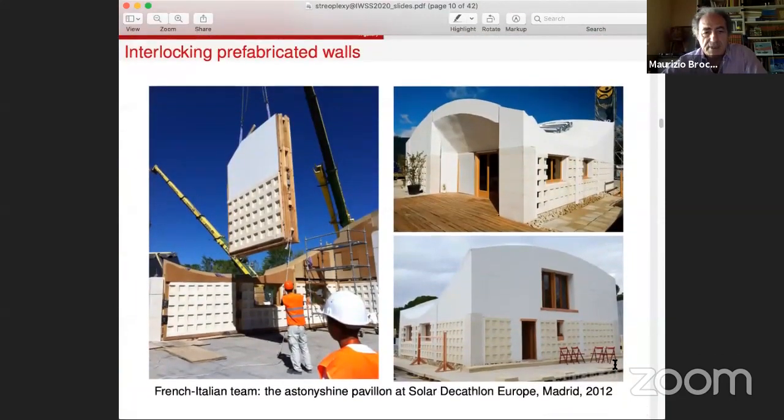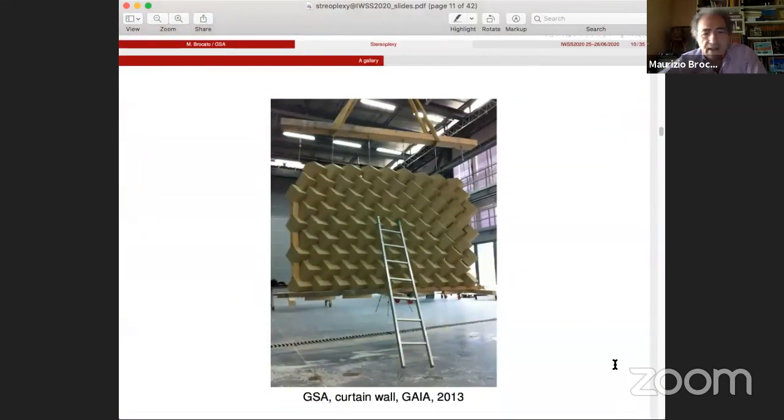Those are built with the same techniques as walls that could be transported, lifted, and that can work under wind and other loads. So again, you understand that the multiplicity of loading that can be withstood by those structures testifies to the fact that they are not only or simply inverted catenary systems. Here is again an interlocked wall, made this time with cubes. It's a very old known assembly of cubes that can be found in treatises of the 17th century also, but that has been recently studied extensively for the high resiliency that the system can have under impact, especially.